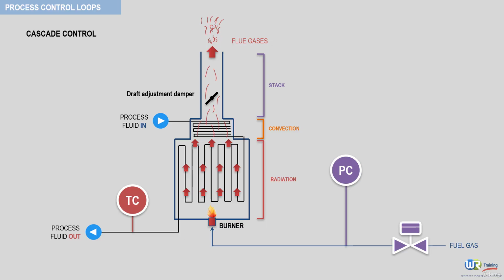The flow of gas to the burners is linked with the gas pressure immediately upstream of the burner. If this pressure is constant, the gas flow will be relatively constant. If the gas network pressure varies, so will the pressure at the burner. The pressure controller then corrects the opening of the gas valve to stabilize the pressure at the set point value. Consequently, the furnace outlet temperature is not significantly modified. The secondary loop is also called the fast loop because it quickly dampens the effects of local pressure disturbances.